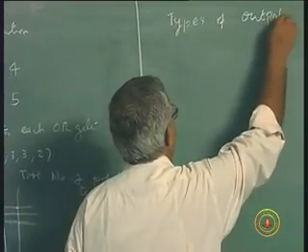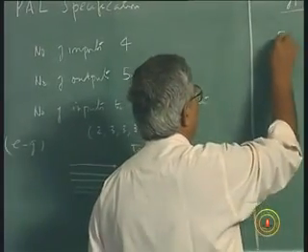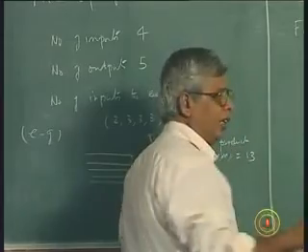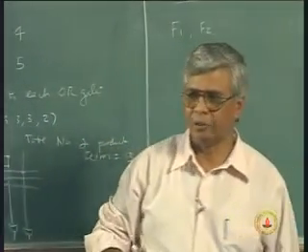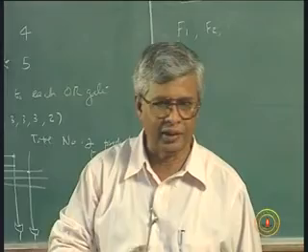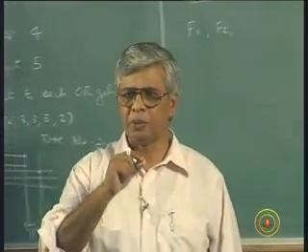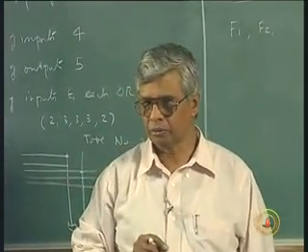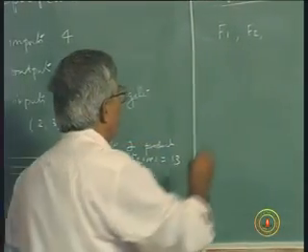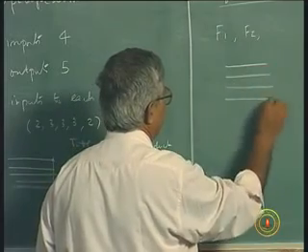What do you mean by that? See, each of these functions F1, F2, etc. We normally, as I said, till now it is only combinational logic. I have been saying combinational logic design using programmable logic devices. Is that right? So we will have an output function in terms of P0, P1, P2, P3, etc. Now, simply like this, each of these is an AND gate.